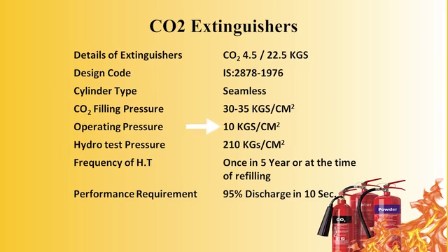Now the operating pressure is 10 kg per square centimeter, and the hydro test pressure is 210 kg per square centimeter. Frequency of HT, hydraulic test: the cylinder hydraulic test should be done once in 5 years at the time of refilling.